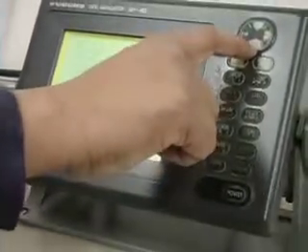The question was: extract geodetic datum from chart and enter value into the GPS. So there are two pages. This is the first page: fixed mode 2D or 3D, disable satellite, GPS smoothing, speed average. By putting the arrow down, you go to the next page. Page number 2: geodetic datum, position offset, time difference, position. So I will choose WGS 84. Highlight geodetic datum, now arrow left, highlight WGS 84, press enter. It is now chosen WGS 84.